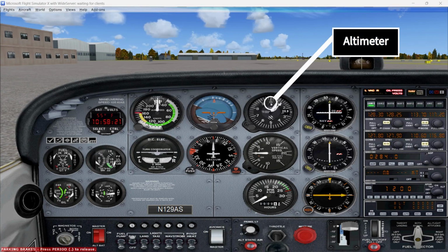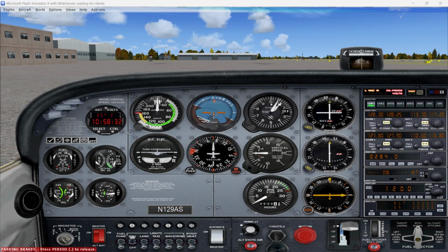An altimeter, or altitude meter, is an instrument used to measure the altitude of an object above a fixed level. Pressure altimeters are found in most aircraft today, but other types of altimeters include sonic, radar, and laser altimeters. Using a pressure altimeter, altitude can be determined based on the measurement of atmospheric pressure. The greater the altitude, the lower the pressure.